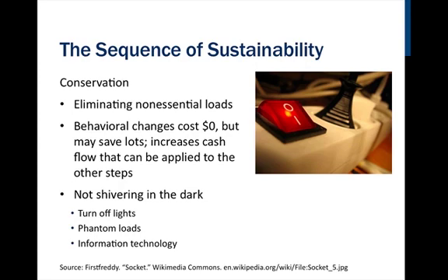Phantom loads are small uses of electricity that draw power constantly. Appliances with a built-in clock, or appliances that power up the second you turn them on, would be a phantom load. A television or computer that powers up instantly does so because it is constantly drawing small loads. To eliminate these phantom loads, you can use power strips and open the circuit so the electricity won't flow to these appliances when they are not in use.